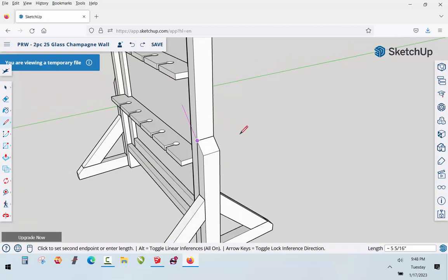So anyhow, that is obviously a little bit confusing. So now we've drawn a line on the red axis, and then we want to rotate. So we have to select the item we're rotating. That item turns blue. We can hit the Q key on our keyboard, and you can see now we are on the blue axis because our protractor is blue, and we need to be on a different axis. And this is at the top view.